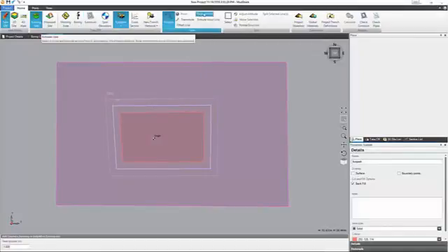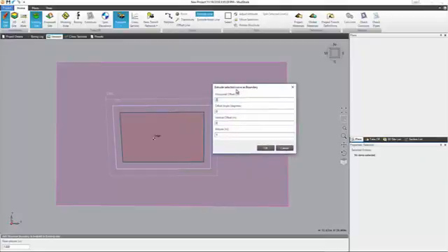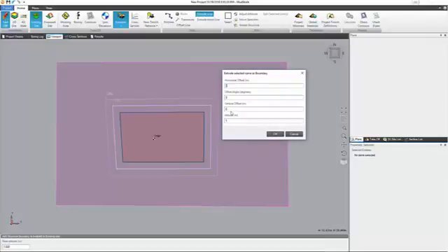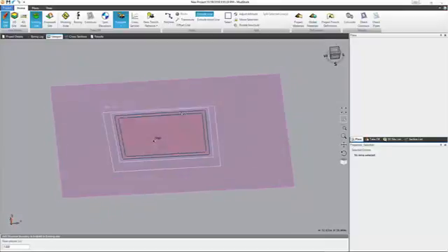What we can do is go in extrude line. Now what this does is it extrudes the selected line by the distance you give. So if I pick that, you can see we've got all the same options as with offset line. But let's say we're going to go half a meter out, and we'll go OK. And we've created a footpath around the building.